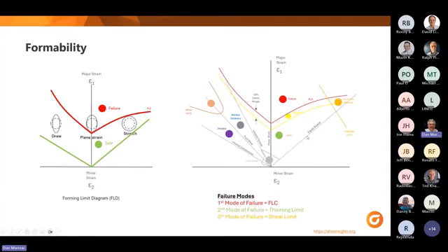Now, we have 5 modes of deformation: equal biaxial stretch, plane strain, uniaxial tension, pure shear, and uniaxial compression. And we will color points plotted in these areas for you as purple, dark gray, light gray, green, red, or yellow. And this is what's commonly known as the first mode of failure, because that means you've stressed the part past its abilities as a material to be stretched.